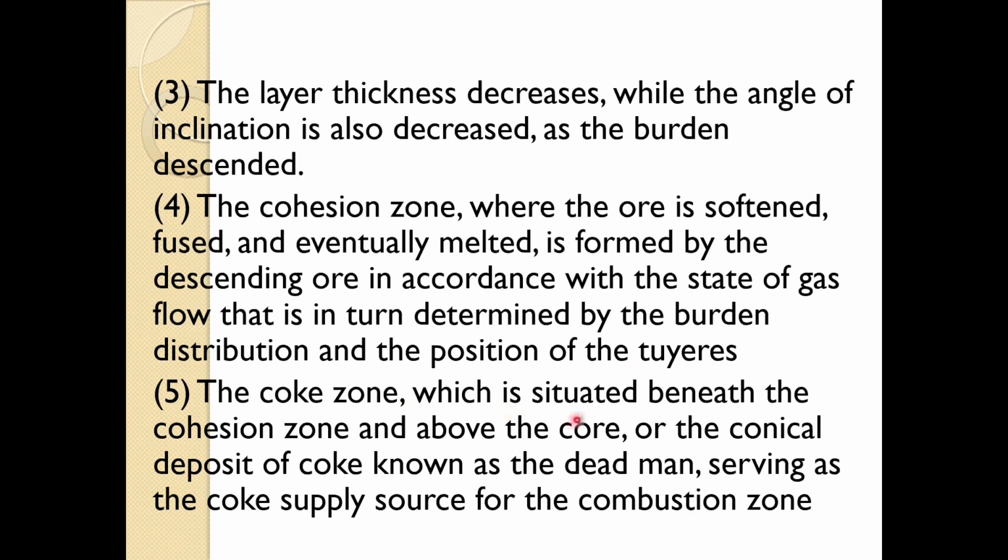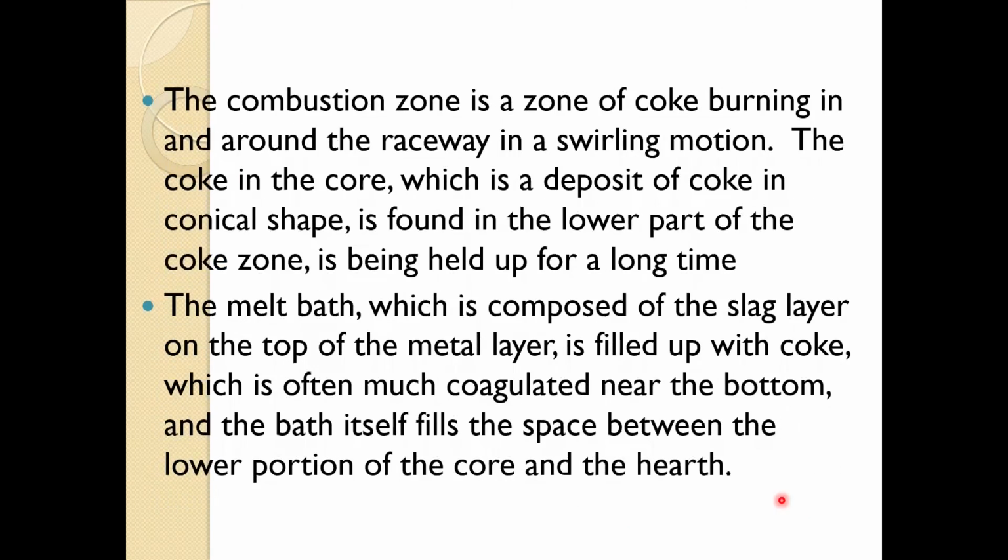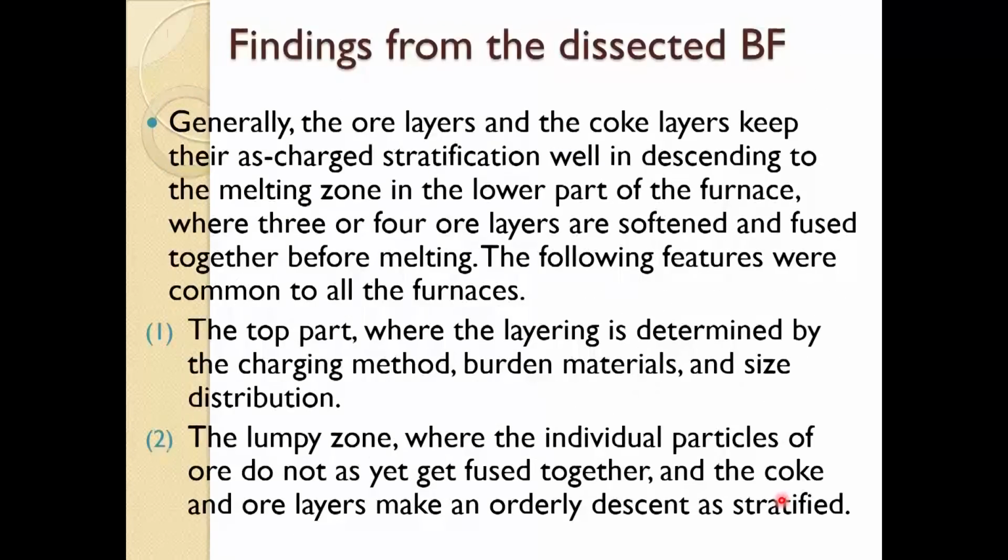The coke zone, which is situated beneath the cohesive zone and above the core or the conical deposit of coke known as dead man, serves as the coke supply source for the combustion zone. So, this dead man is a very important